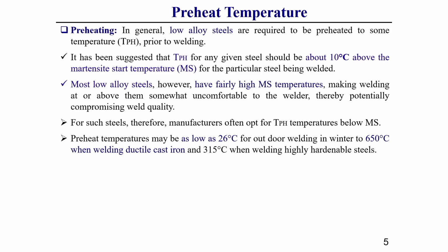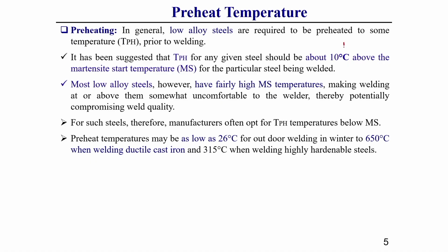Always keep it in mind, generally it is suggested that the preheating temperature should be above, by 10 degree centigrade, the martensitic starting temperature. It should be 10 degree centigrade above the martensitic starting temperature. So it is suggested by the technical community that the preheating temperature, I am writing TPH, should be equal to the martensitic starting temperature plus approximately 10 degree centigrade.